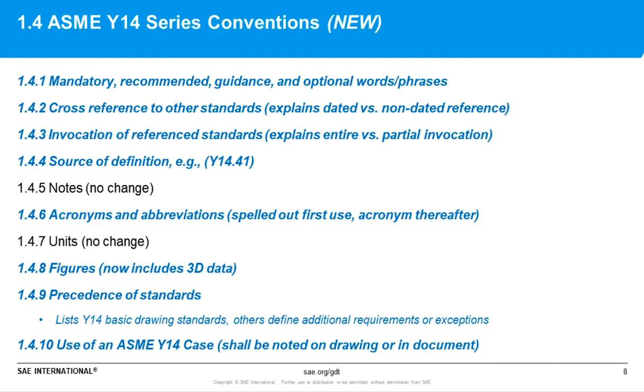Okay, so let's talk a little bit about the Y14 series conventions. So in section 1.4, it addresses mandatory, recommended, guidance, and optional words and phrases. And then 1.4.2 addresses cross-reference to other standards and explains dated versus non-dated reference of standards.